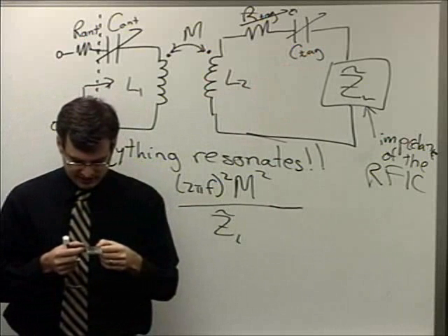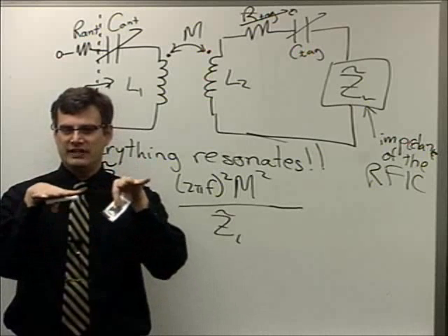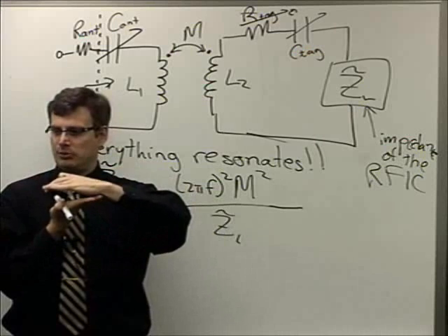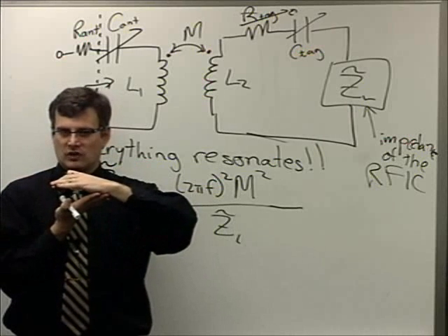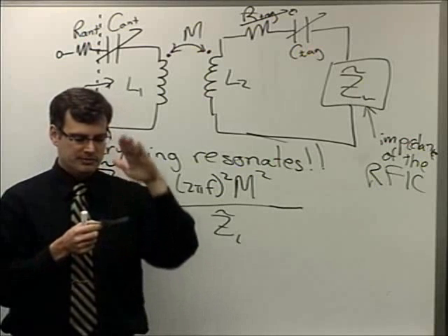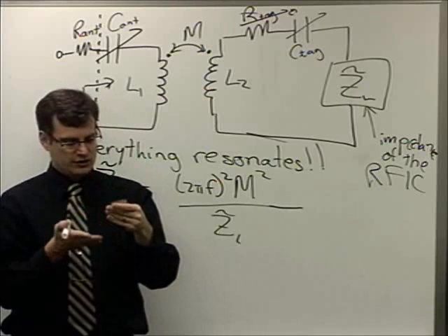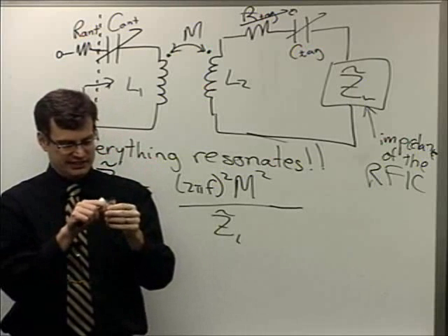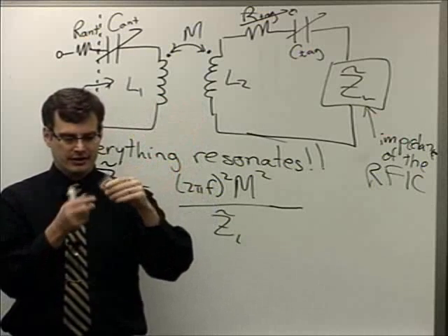You can see it because they use the plastic substrate as the intervening dielectric between the two parallel plates, the insulating dielectric. And here's the problem with that. There's an aluminum stamped foil trace glued to the top, and another aluminum foil trace that actually has a yellow backing on it, so that's how you can turn it over and see that that's the capacitor.